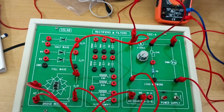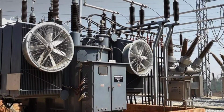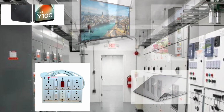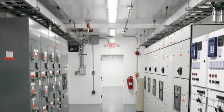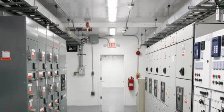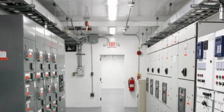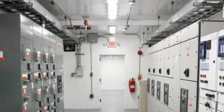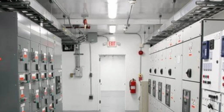The first and most important thing is, by using the bridge rectifier, we are converting the alternating voltage into DC, that means pulsating DC. By converting this, the electronics applications will work. So by converting the AC to DC, how much DC will be obtained in the output? To find that, we are finding the average value. I am repeating this once again. The purpose of finding the average value is, when we are converting from AC to DC, how much amount of DC is obtained in the output. So for that purpose, we are calculating the average value.